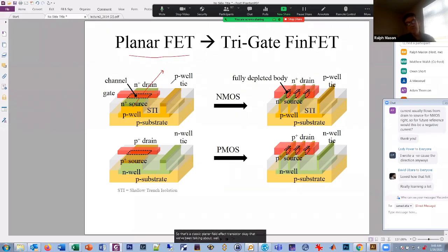Well, it turns out as transistor channel lengths got smaller and smaller, it got hard to control this channel that was under the gate. So this little dashed box in here, that's the channel. And that channel, this dimension is the length, right? This is the length right here. As it got smaller and smaller, forming the channel underneath it, particularly turning it off, got harder and harder.